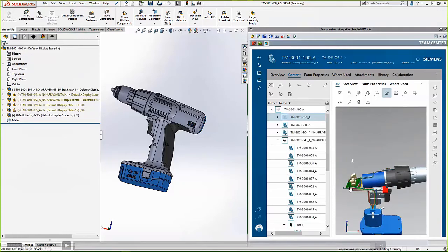And you can see at the end from a visualization format, there's that same board that you saw inside SolidWorks. You now have a CAD neutral representation inside Team Center. So anybody with access to Team Center and access to this bill of material can view and understand what this assembly looks like. If you combine that with the change management, you can have that single change process that lets you perform a where used to see where that product is used across your entire company. Then you can kick off a change and know exactly what is affected by it. So it's this mechanical information, this electrical information, this electronic information, this software information that's impacted by this change, and automatically notify those users, here's what we need to go do.